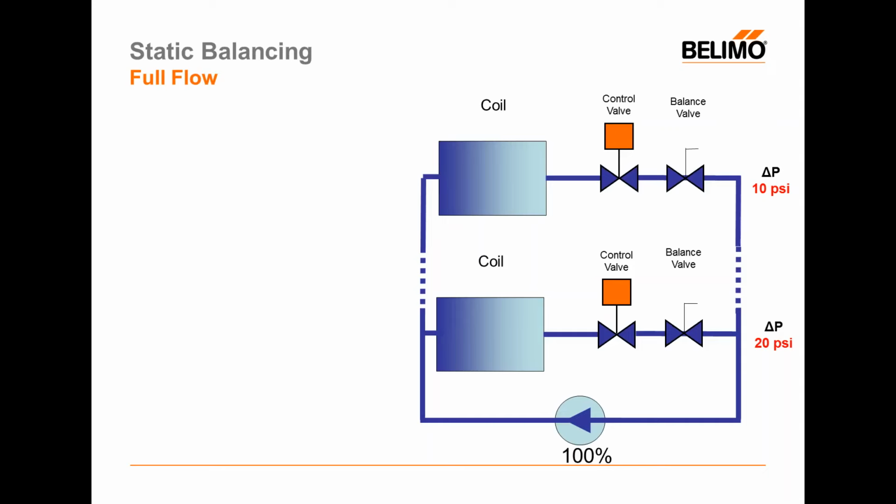So we're looking at the first floor and the 10th floor of our building, and we're going to juxtapose those because they're going to have vastly different behaviors, even though we're going to assume all the coils are identical, the control valves are identical, and the balancing devices are identical. The last thing I need to explain on this chart is that on the right-hand side we're displaying a couple of different delta P readings. What you're looking at is the pressure drop across the branch run.